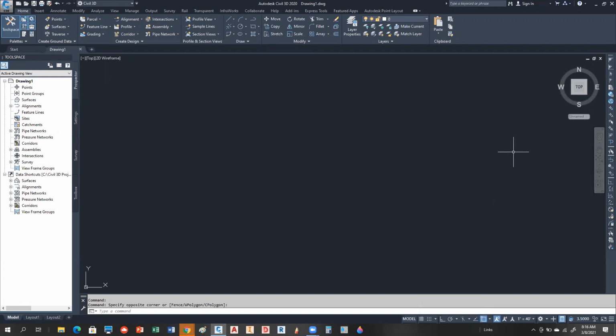One thing I should also mention, you can snap to an object point in Civil 3D using a normal O-snap, but the one you would use is what's called the node O-snap. Actually, it won't snap to any of these other things. Well, actually it will. You have to be careful because endpoint could snap to the endpoint of the symbol. So if you want to snap specifically to a Civil 3D point and get to the right point on it, you would use the node O-snap. We're going to be utilizing combinations of these as we get into that.